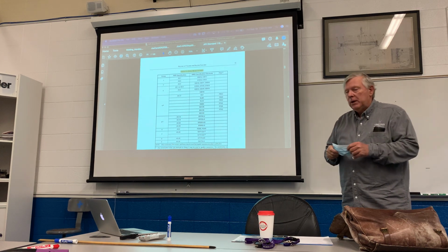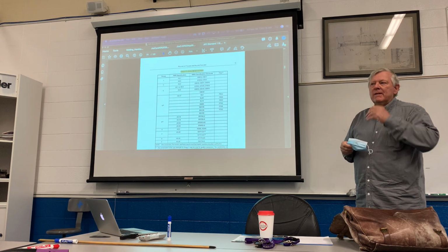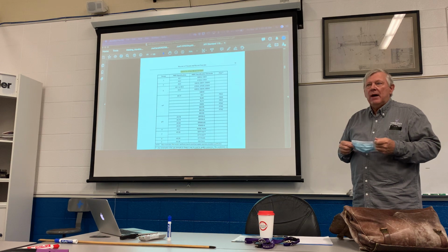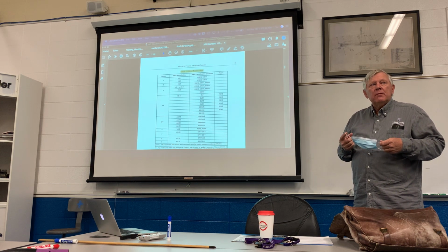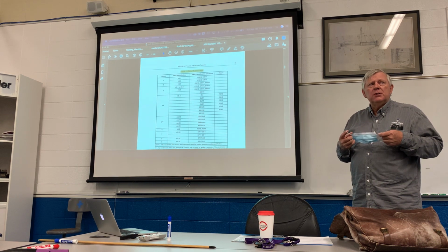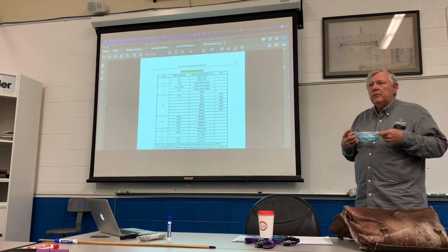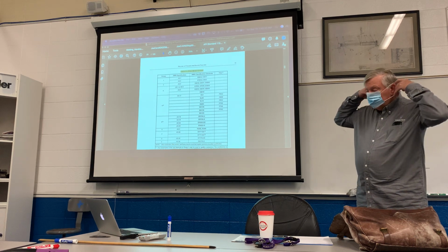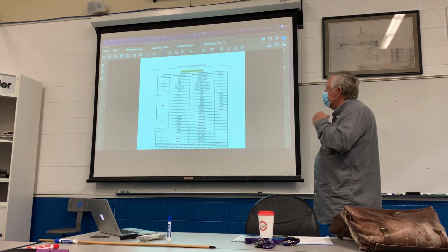I talked to you about preheat. I talked to you about travel speed. Can some of those things be slightly different and still be within the procedure? Sure, they can. You have to know those specific things.